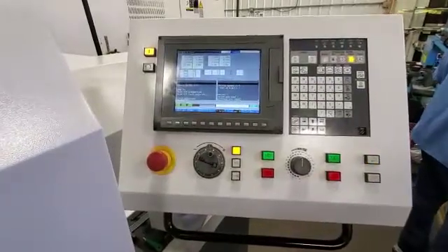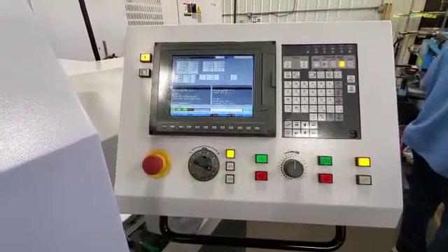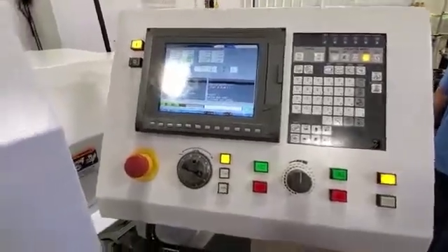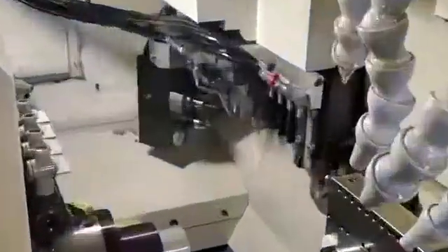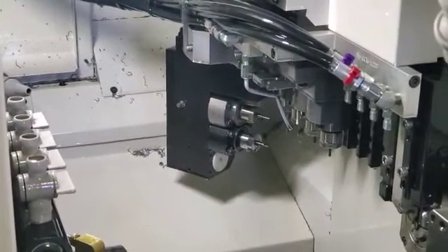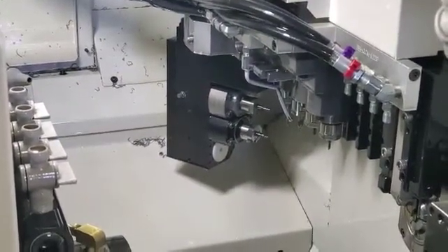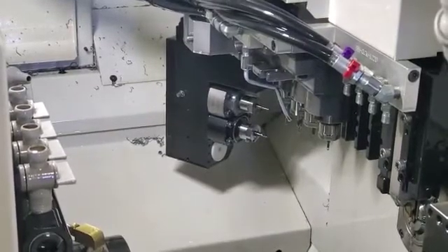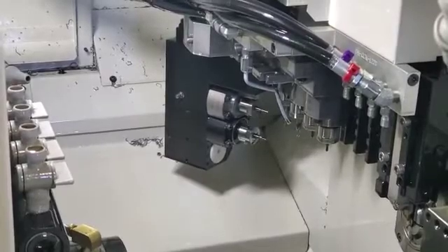In this video, we're going to go over how to touch off tools on our angle drop-down tree on the Work Center 302. Right now we've got a job set up in here with that drop-down tree and two end mills in it. For this job, it's set to a 55-degree angle. So that's all set, and we're going to go over how to actually touch those tools off.